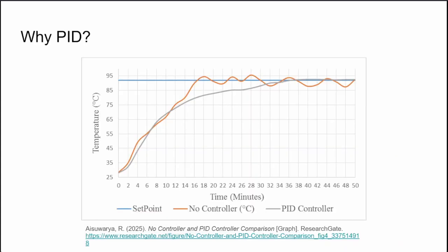So here's an easy to understand example of why PID controls are important. Let's say you're doing some cooking and you want to keep a pot at a certain temperature. How do you decide the level you should put the stovetop at? One way is to stick a thermometer into the pot and set the stovetop to high when we're under the target temperature and then to off when we're above it. While this guarantees that we'll be around the target temperature, we'll fluctuate a lot, as seen by this orange line, because we're only having completely high and completely off states.